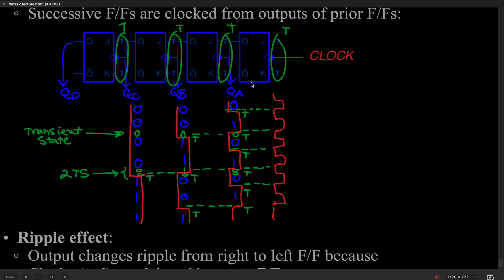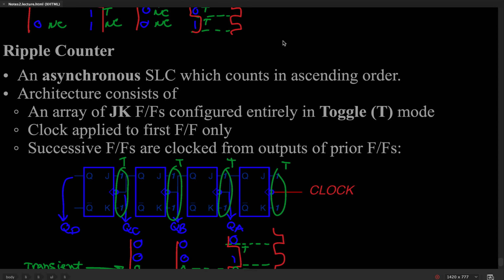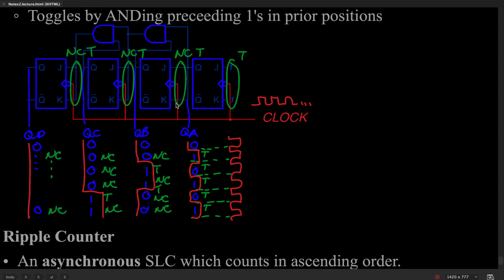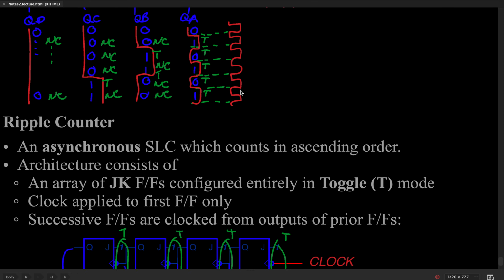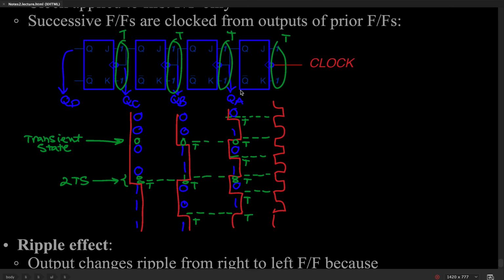First of all, the first stage is exactly the same as the first stage of the earlier circuit. Comparing this one with this one, they're identical. So therefore, I know how this one works. As I apply a clock pulse here on the negative edge triggering of this waveform, I will get a toggle. Toggle, toggle, toggle, toggle, toggle, toggle. This causes a waveform to be frequency divided by a factor of 2, resulting in a clock waveform that is twice the period of the clock as we saw earlier.